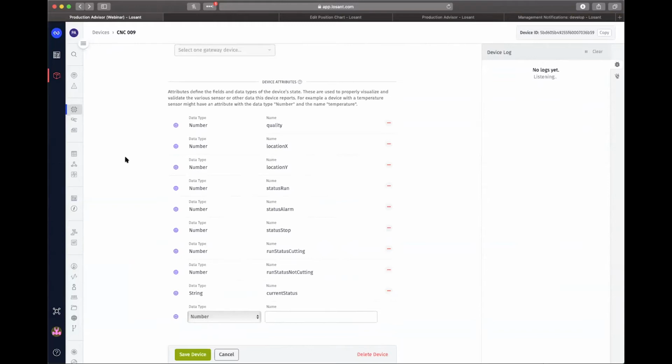Ethernet IP as a way to talk to the Allen Bradley PLCs that the CNC machines would be using, but it could also be using other protocols like OPC UA or Modbus, whatever your equipment is using as a way it can collect that sensor data. We can go get it and then bring it into the edge device. The edge device then processes it locally and then sends it up to the cloud.